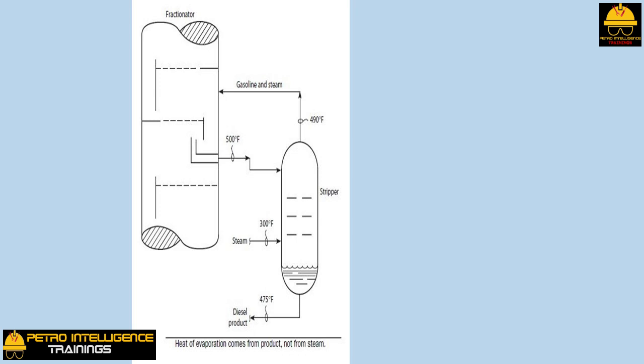The heat of vaporization of the gasoline cannot come from the steam, because the steam at 300 degrees Fahrenheit is colder than the diesel oil at 500 degrees Fahrenheit. The heat of vaporization must come from the diesel oil product itself.